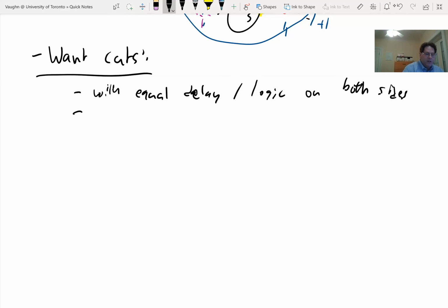The other thing is that you can balance for area. I told you registers are plentiful in FPGAs, but they're still not infinite. So you can sometimes wind up with multiple places to cut that will cut your critical path reasonably evenly. But basically, if some of those cuts have fewer edges, you basically save register count.